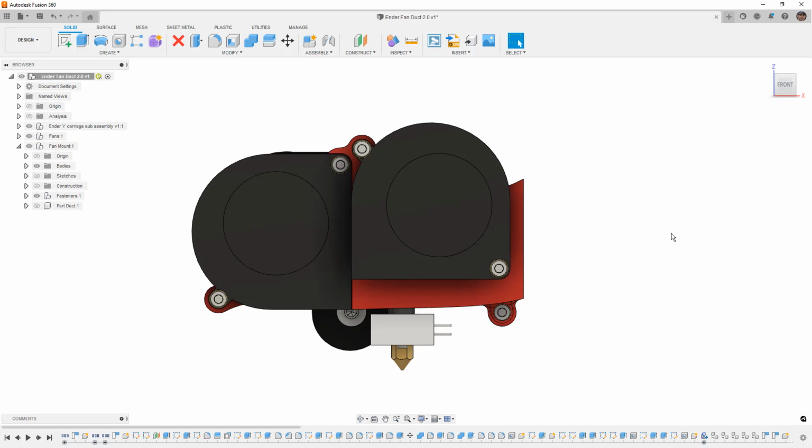So with that in mind, I'm going to just build out the inside volume, the place where all the air is going, and then worry about the outside shape on its own, and then I can subtract the two, take away that inside volume. The second thing that I need to think about are going to be things like obstructions or things I want to avoid.